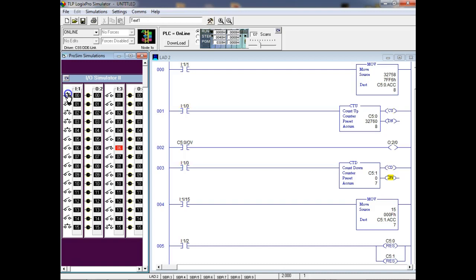All right. And of course, the problem is it's still going to have to go past 0. So the down counter has to go what? It's got to be more negative. But what we're doing here, now it appears to be a down counter. So you see how I set that up? What I did is I loaded this with a positive 15. I set my preset to what? 0. Everybody understand that?